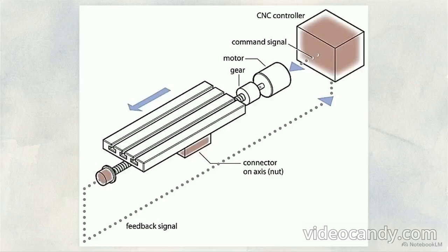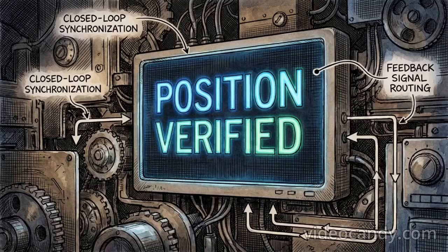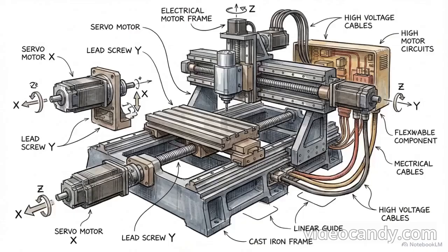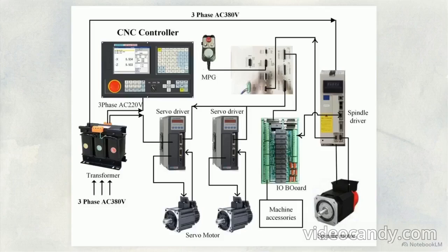This diagram illustrates the feedback system, which relies on highly precise velocity and position transducers. A linear encoder continuously monitors the actual physical location of the cutting tool at any given microsecond. This feedback schematic shows how those exact physical coordinates are sent immediately back to the MCU. The MCU continuously compares the true feedback value against the desired command position, instantly augmenting the amplifier signals to correct any detected deviation. Achieving 0.0001-inch resolution requires this relentless closed-loop paranoia, constantly adjusting and verifying the machine's exact location.